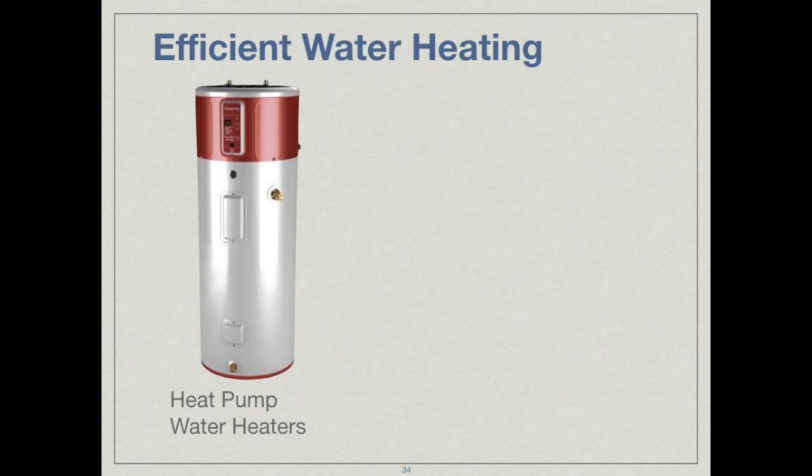This is why in most places you want to put the heat pump water heater in a buffered space, a place that's not heated deliberately. It could be an unheated basement or an unheated garage, the kind of place that stays fairly warm, in the 40s, maybe 40 degrees Fahrenheit, and doesn't get much below 40 degrees Fahrenheit. These systems will still run very effectively. Even though they make that space a little bit colder, they don't affect the temperature inside the building.